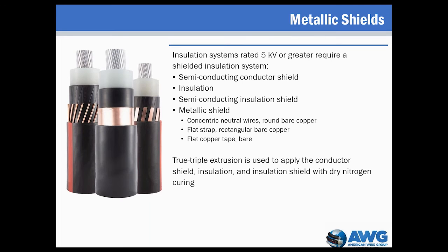To properly distribute voltage stress in the shielded medium voltage insulation system, a metallic component must be applied in direct electrical contact with the insulation shield.